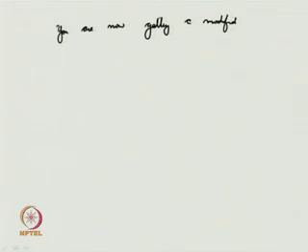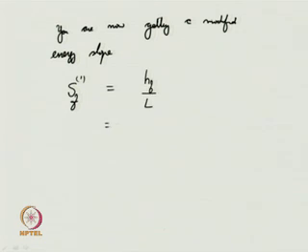So, once you get this quantity, you are now getting a modified energy slope as mentioned earlier. So, SF, let me give this as 1. This is equal to S1, which is equal to delta y plus k into alpha upstream V upstream squared by 2g, and so on.